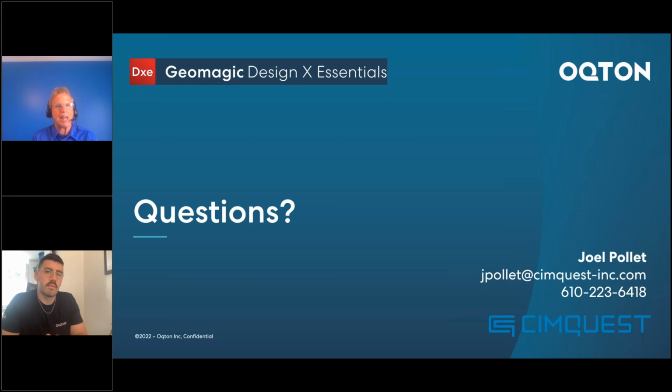So you can take a scan in from a scanner, bring it into Geomagic Essentials. All the 3D printer generally cares about is that you have a scan that can form a volume, right? A fully enclosed scan. In fact, some scanner processors can even close holes for you, but you could use Geomagic Design X Essentials also to prep models, where you're filling holes, trimming out bad scan, and then resaving out another polygonal file, another STL file, to then go to a 3D printer as opposed to going to a CNC machine or into CAM software.